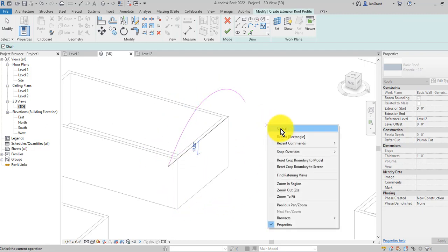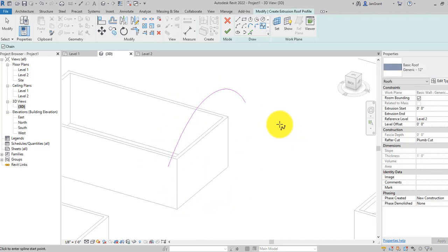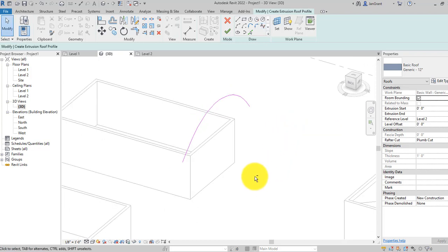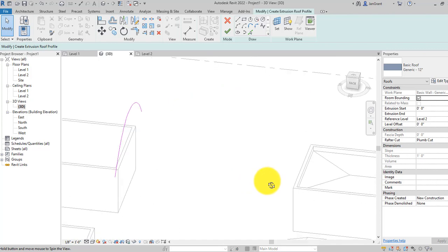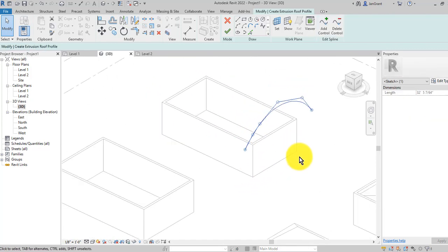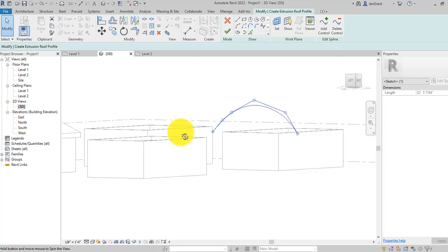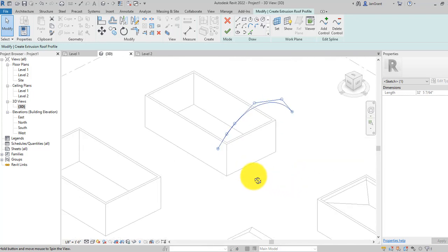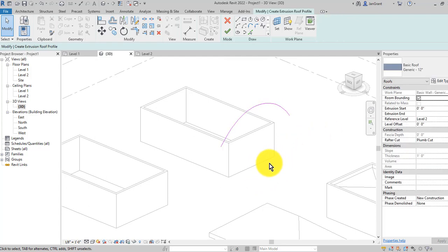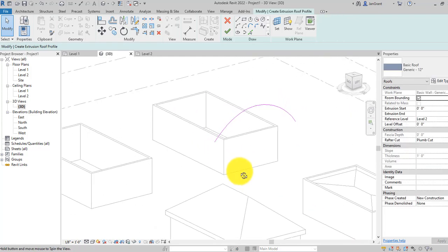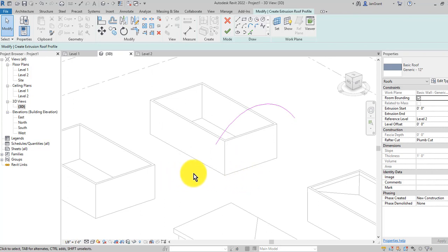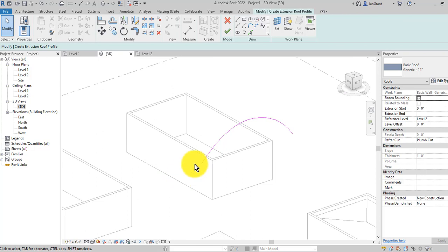At the end, I'm going to right click and cancel and orbit here to see that there's my side. And guys, just so you know, if you select an object before you start to orbit, you get a little more control over orbiting. See, if I didn't have that object selected and I went to orbit, well, now it's read that work plane, but it could go all over the place. So there's my profile that's set up. It could be a straight line. You go ahead and have fun with this. If you want to use straight lines and create a kind of zigzag roof system, you can.